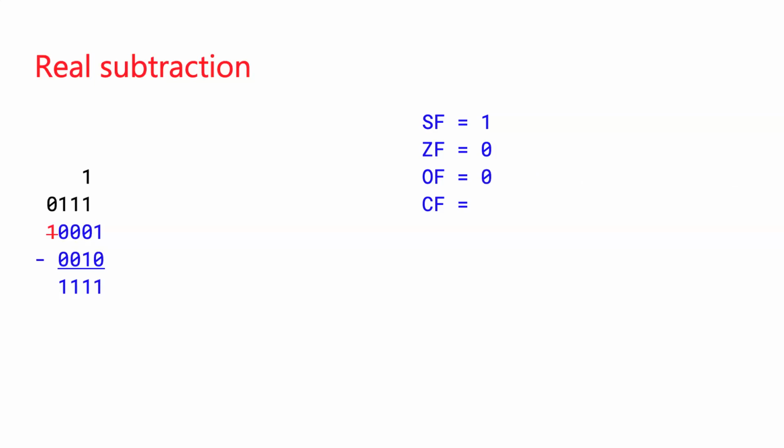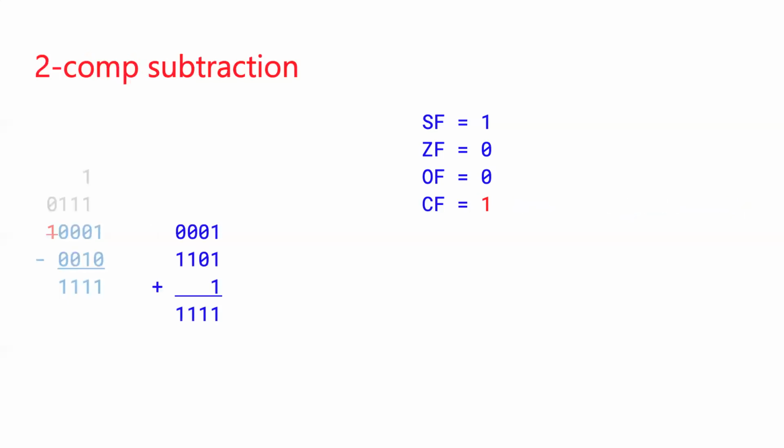Normally for the carry flag, at least for Intel, we think of this as, did you borrow out of the high order digit? And here we had to do this math. So we would end up with a carry flag of 1. And that's obvious if you do this with subtraction, binary subtraction, and we're kind of rewinding a few weeks here, maybe a month and a few weeks. But remember, you could also do this with addition of a -2. And we'd like to get the same result.